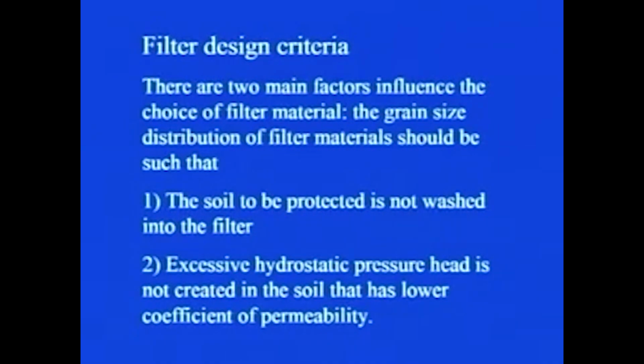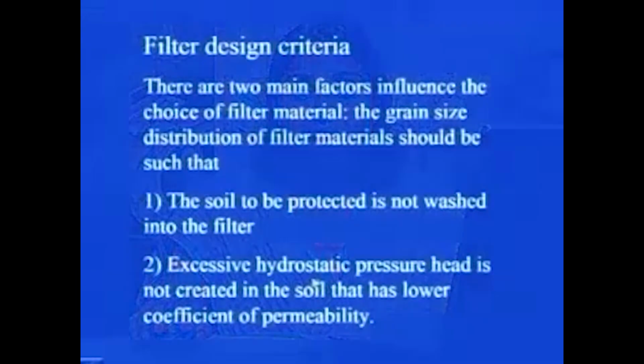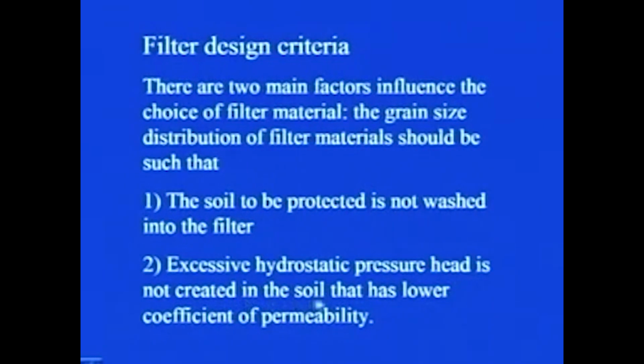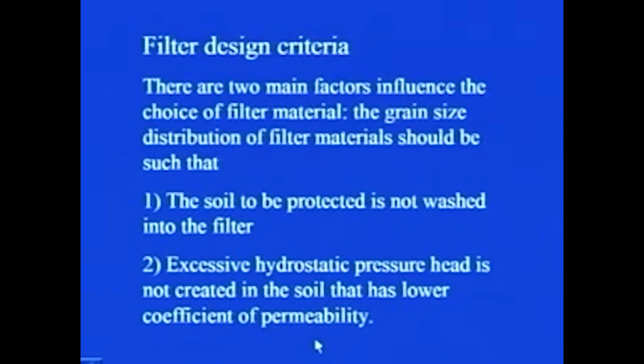In case you are using this granular fill as the filter material, then only this filter criteria you need to keep in mind. First is that the grain size distribution of filter material should be such that the soil to be protected is not washed into the filter, that is, the soil which is getting mixed with water should remain in the backfill region only. Then excessive hydrostatic pressure head is not created in the soil that has a lower coefficient of permeability. So, that also you must take into account.